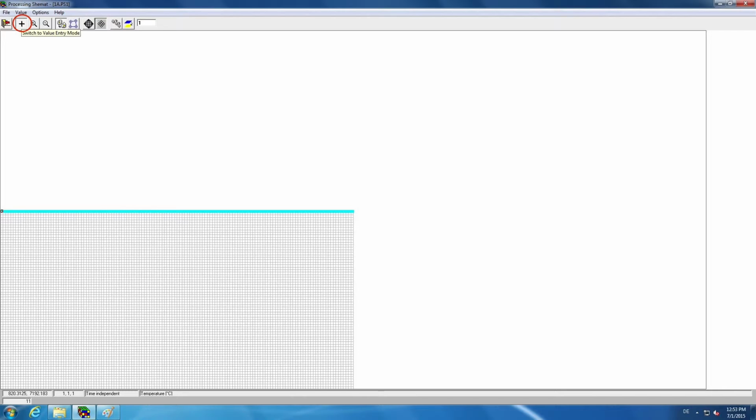Information on each cell is obtained by holding down the Shift, arrow up, key of your keyboard and pressing the left mouse button. This opens the cell information dialog box. Holding down the Control, Steuerung, key of your keyboard and pressing down the left mouse button opens the Search and Modify Cell Values dialog box. It allows you to modify either individual cell values or values of cells which fall into a specified range.